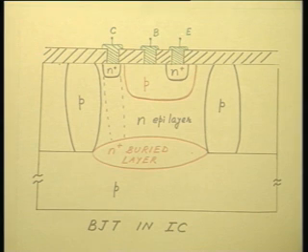So, all these parasitic capacitances will have adverse effect on the speed of the transistor. And if you have this junction isolation, then you have a large junction capacitance associated with the collector N and isolation P. The PN junction capacitance will tell adversely on the speed of the transistor.